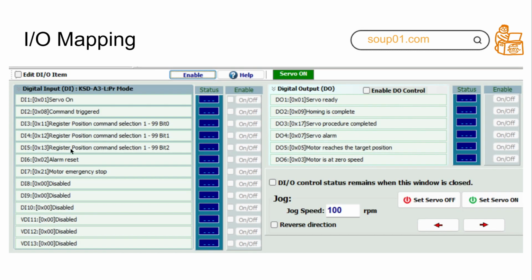Okay, so here's the IO mapping. In the servo drive setting of the JTEKT servo motor, you can feel free to edit any digital input or digital output to any signal that you want. That depends on applications. So I would like to notice you that you do not need to 100% follow what I make this time. You can create your own application, with any free IO mapping.